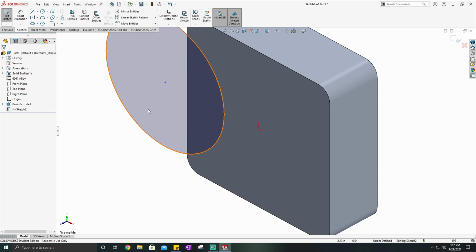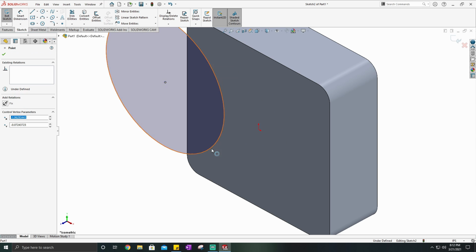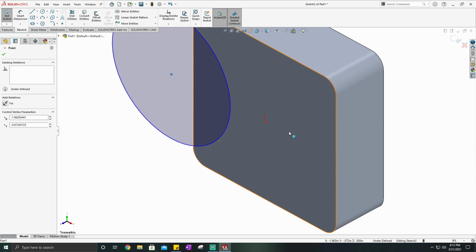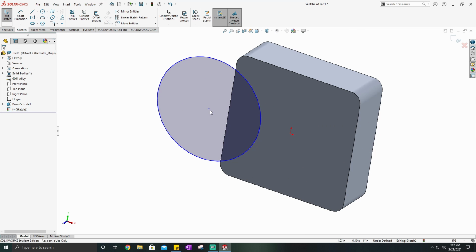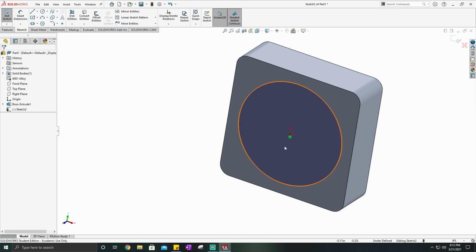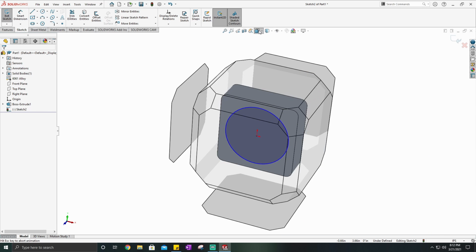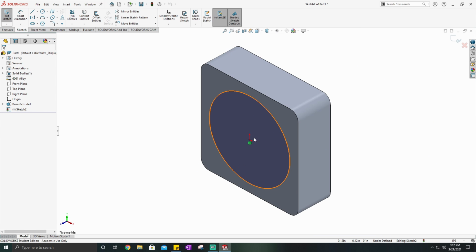And so let's say I just wanted to put that back without dragging. I can just click on the midpoint, hold control. Typically, midpoint. Okay, that's weird. It's not letting me. Typically, it lets you select the origin. I don't know why it didn't do that there. But either way, we just dragged, dropped, made it coincident.